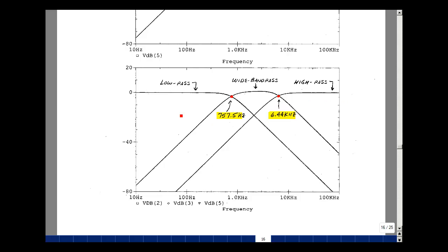Now, playing music through these 3 speakers, our ears will add the results together. So the results of the first speaker, plus the results of the second speaker, and the result of the third speaker, moving columns of air, our ear will then sense the summation of those 3. And that's how a crossover filter works. And this is supplemental problem 12.4.